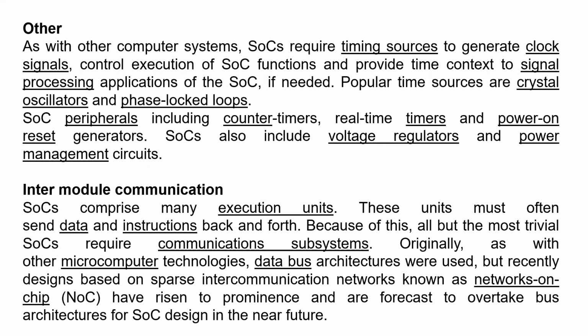So what does bus type of architecture mean? General microprocessors follow bus type of architecture for communication. That means it has three types of buses: data bus, address bus and control bus, to communicate with the different components within the system.